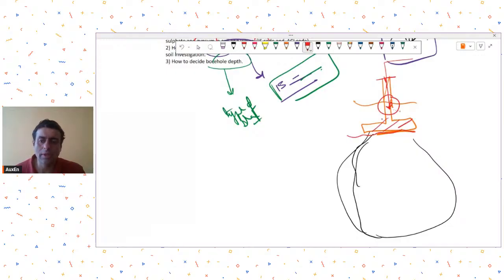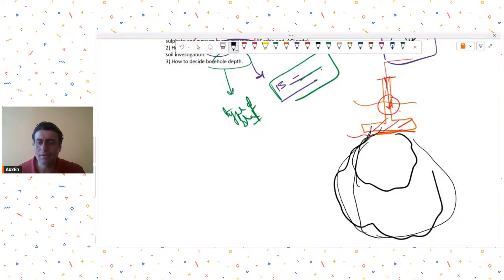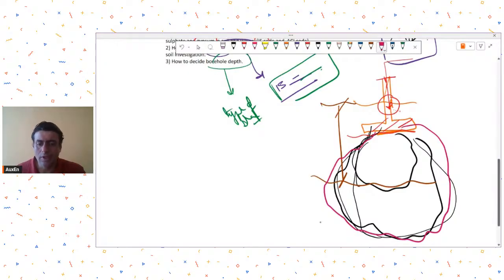So depending on that, for smaller column loads, the pressure bulb will be smaller, and for larger column loads, the pressure bulb will have a larger area, isn't it? So if your column load is small, your soil exploration depth may be limited only till here. But if your column load is greater, its pressure bulb will be such that you may require even larger depths.